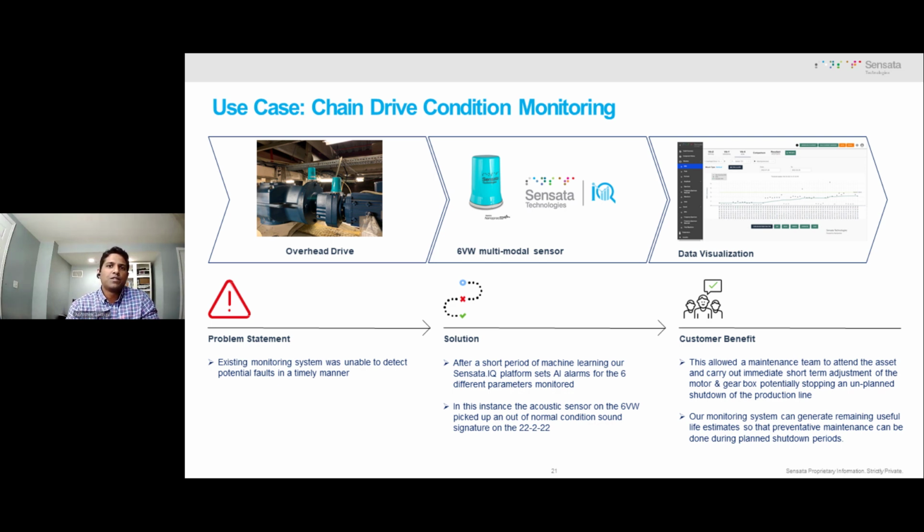And we were able to take rich vibration data for low frequency vibration. And then also we had an acoustic sensor, which was taking data in the high frequency ultrasonic range. And also we were monitoring the temperature and speed using our Sensata IQ dashboard.